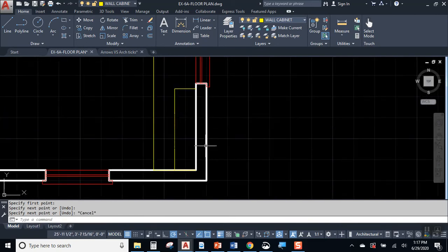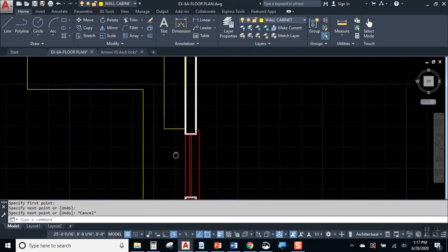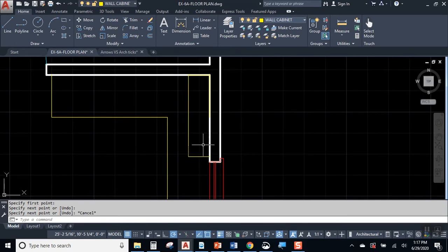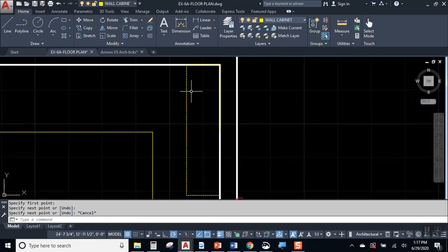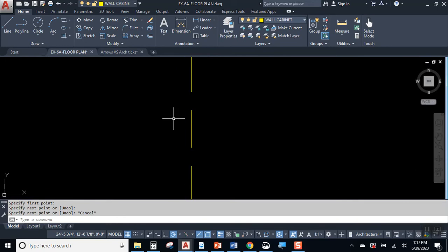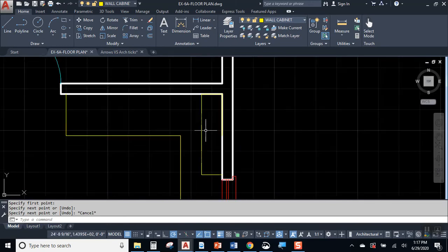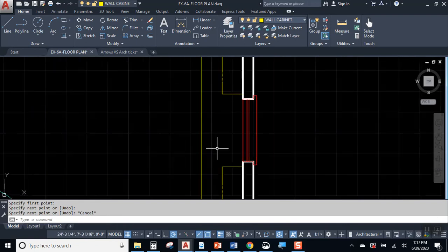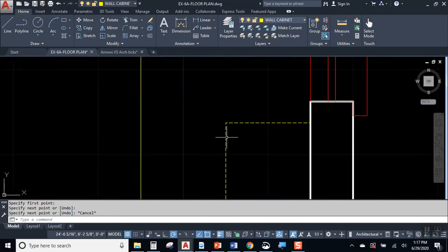Right, now I know what you're saying. You're probably wondering why you don't see dashes. Because didn't we make this a layer that was hidden too? So if you don't see dashes, you didn't mess up. Just look a little closer. See what's going on there? There are a bunch of dashes, but they are tiny, right? Because AutoCAD is generally set up for mechanical drawings of small mechanical parts. At least, that was the idea when it first came out.